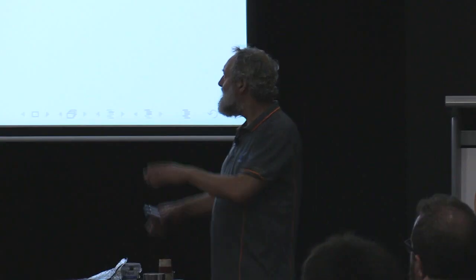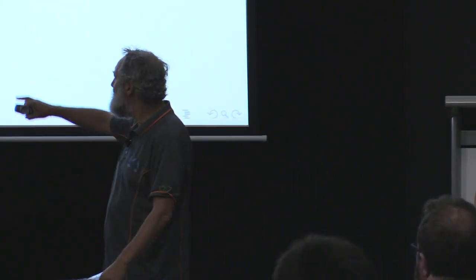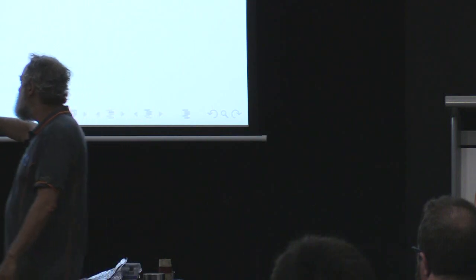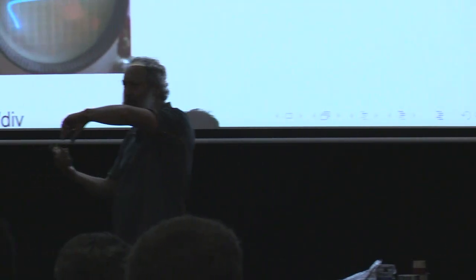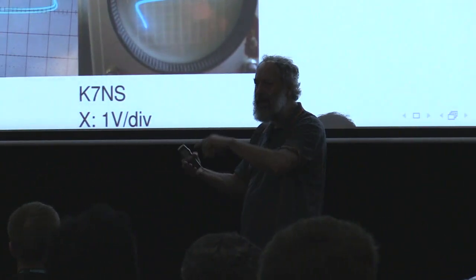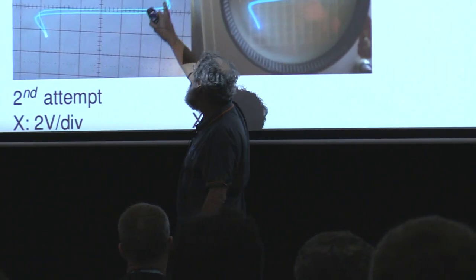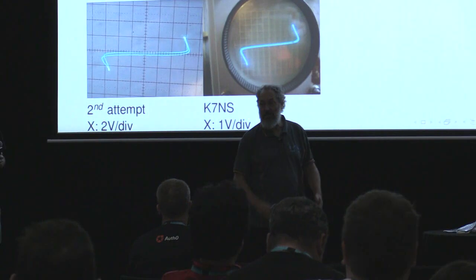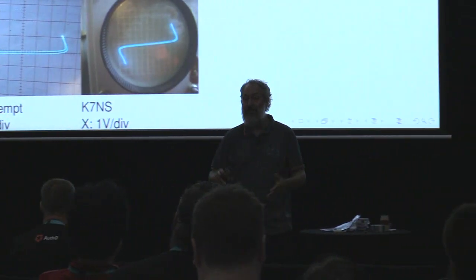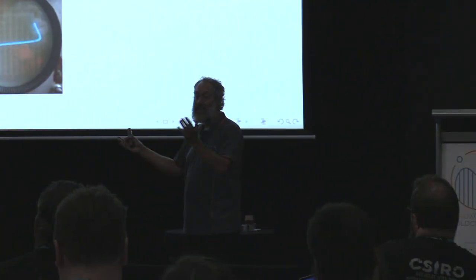There's also, I didn't go through, we ran out of time, but you can make negative resistance elements. And if you bias your zinc oxide plus a thing at the right time, you can bias your operating point to here and actually get a gain element and build oscillators and regenerative receivers and amplifiers. But I didn't get time to talk about that.